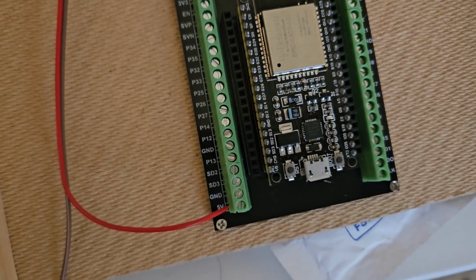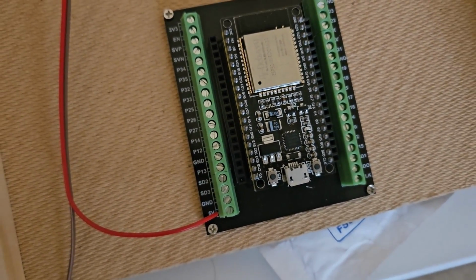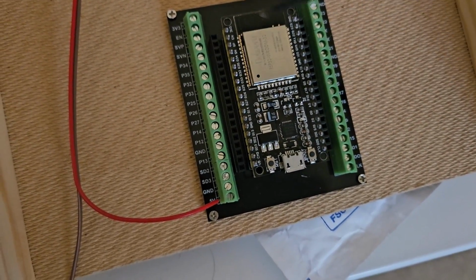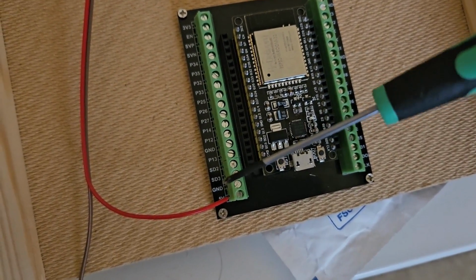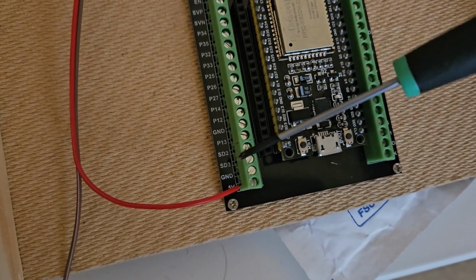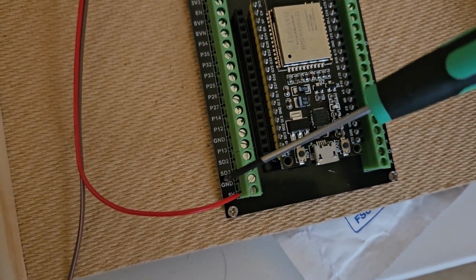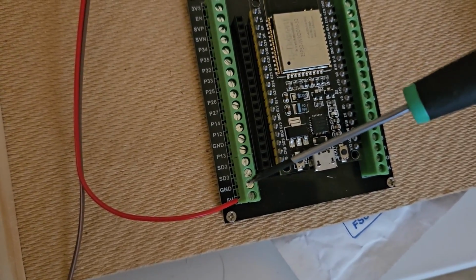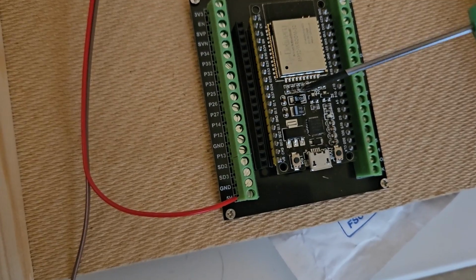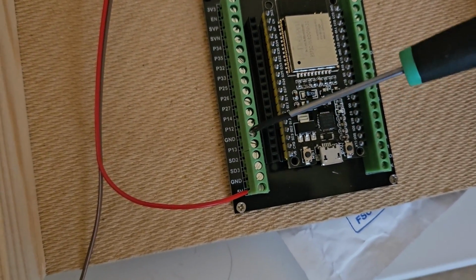Down in this bottom left hand corner, sometimes you've got to be careful with labelling there, because I'm coming to connect power to this thing now. Down here, second up, you've got your 5 volts at the bottom, and second up, if the camera's picking that up, they've got GND, which indicates ground. Now that surprised me, because there isn't a ground there on this. The ground is a bit further up.